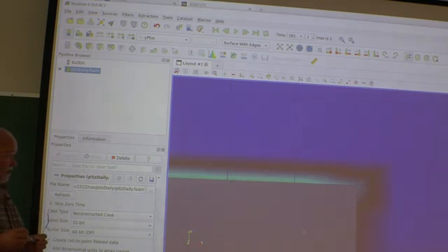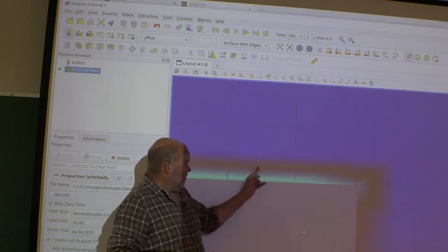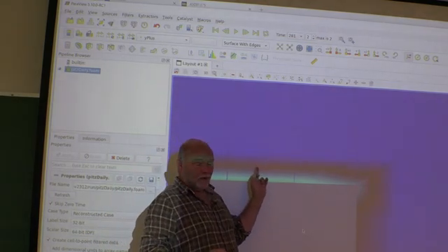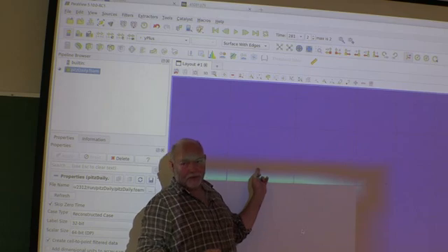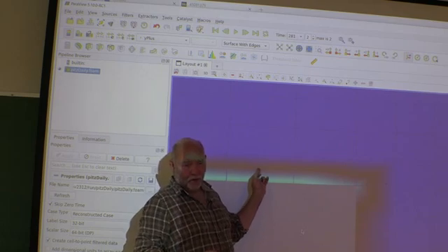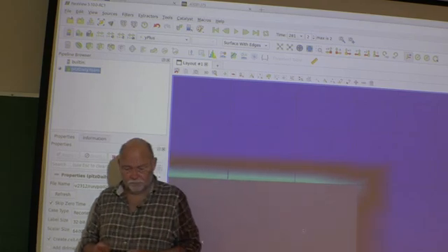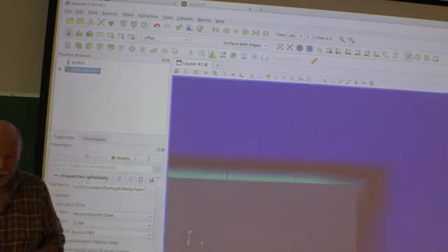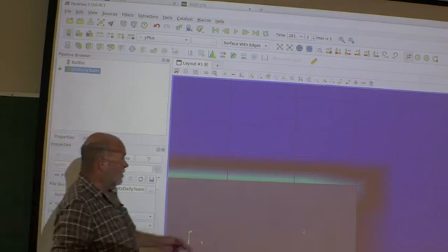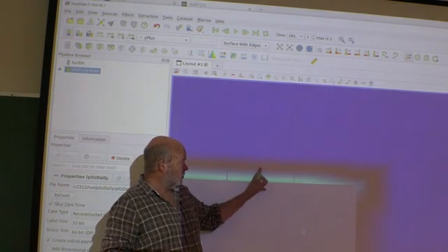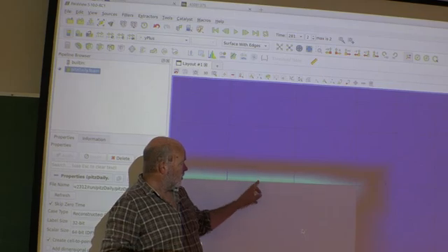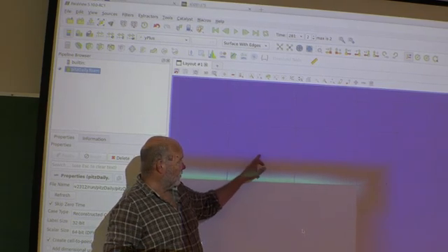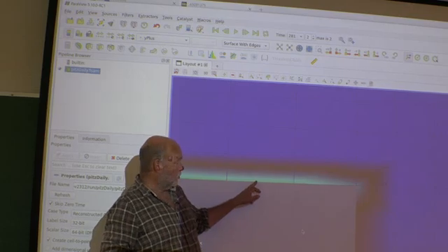So, as I say, the y plus value is given in the cell centers. OpenFOAM is a co-located program, meaning it puts all your variables in the center of each cell. So that's why it has interpolated from 0 here to a value on the wall.